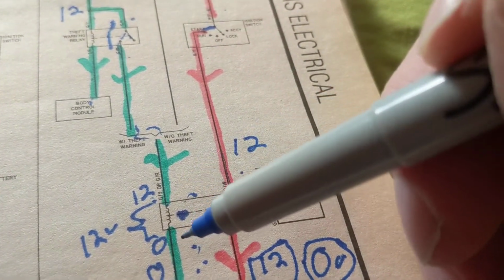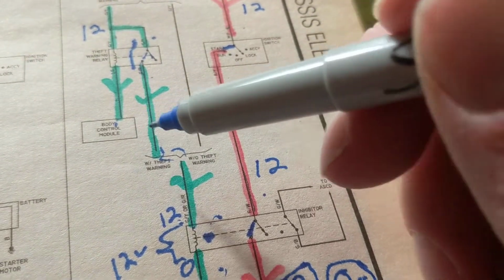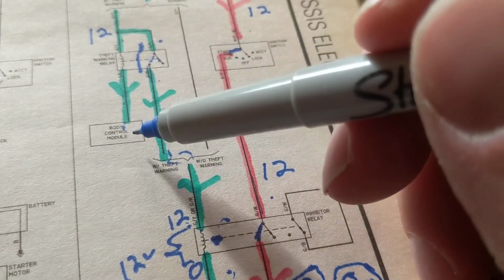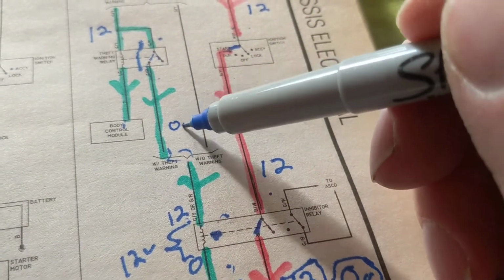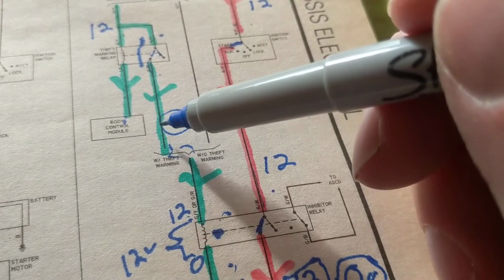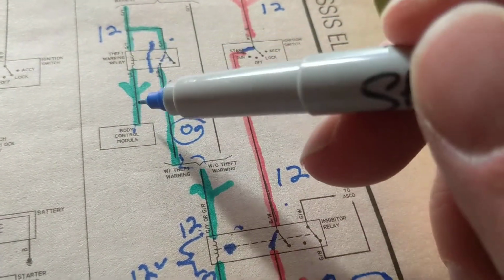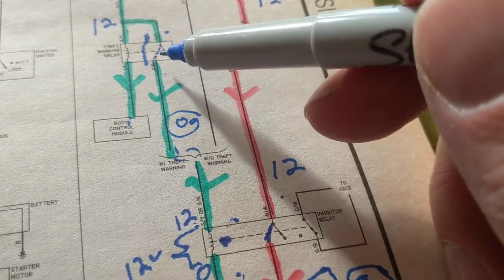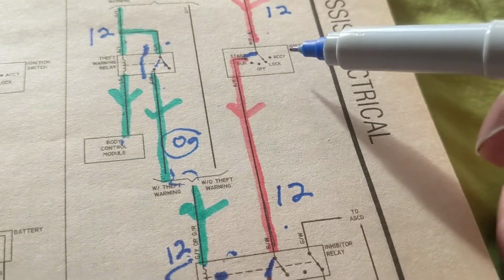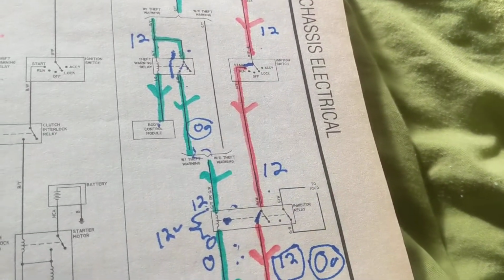If I measure 12 volts here and 0 volts, that tells me what? That tells me that this works, the computer. Because if this wouldn't work, I would have 0 volts here, not 12 volts, right? The fact that I get 12 volts means this works. This gave it a ground. This is energized. If this is energized, this is energized, and it gives me this. That's why I say, try to look at the schematic as best as possible. It's difficult, but that's how you diagnose.